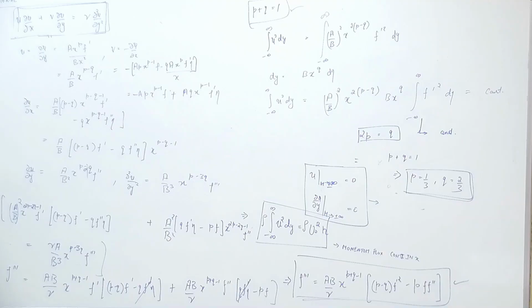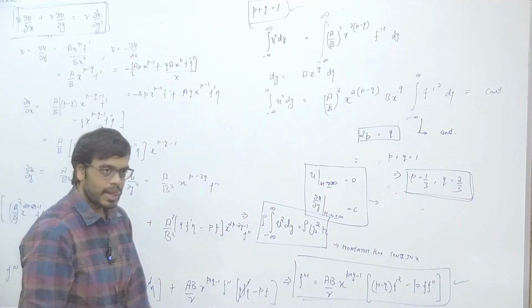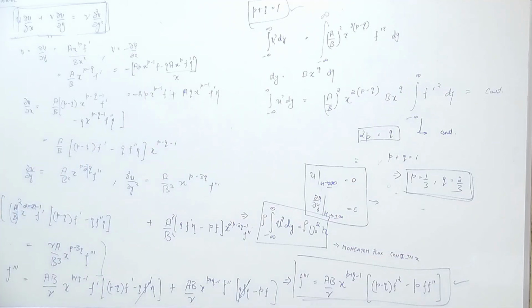So, this is not the second condition. In the flat boundary layer case, the second condition came from... where did we get that delta is square root of x? How did we get that delta is square root of x? If you go through that, your u infinity was constant, and basically what you began with was this guess assuming both P and Q are equal.